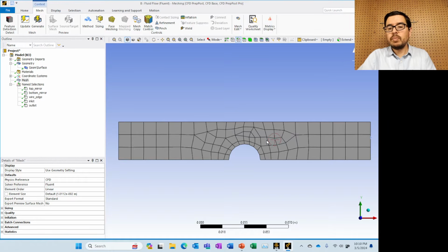What we're going to do is similar to what we did in our last example, where we added elements along the surface or along an edge where we thought there would be some boundary layer effects. So over here and here and here, there's going to be no shear, so it's not as critical. But around this semicircle here, we're going to have a no slip condition, and we would like to kind of be able to capture what's happening physically in a boundary layer. So let's go ahead and add an inflation there.